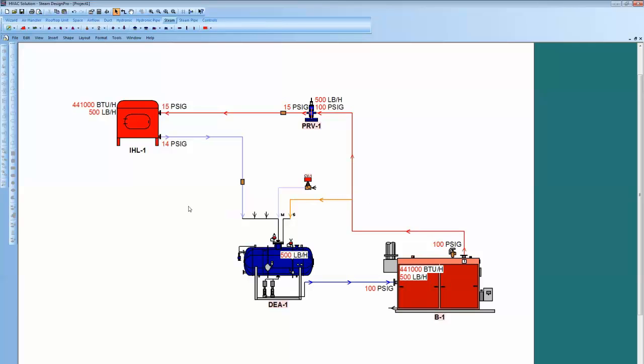The third major item, you have to have some load, some utilization, process load. This a lot of times consists of coils and heat exchangers. And then last of all, you need to have some condensate recovery method. How do I get the condensate back to the boiler? Deaerator, boiler feed pump, condensate pump, we'll work on that.